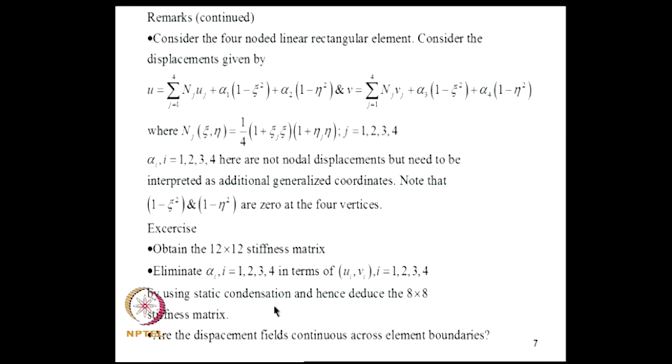In using this element you may notice that we can continue to use the consistent mass matrix that was derived using only this approximation. Kinetic energy can be characterized using only this, whereas the strain energy will be computed by an alternative representation of the displacement fields.